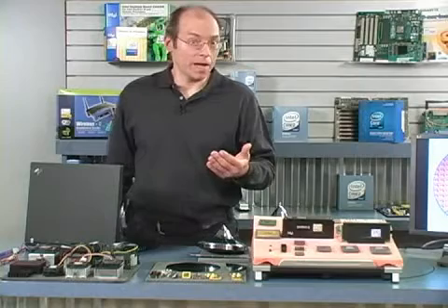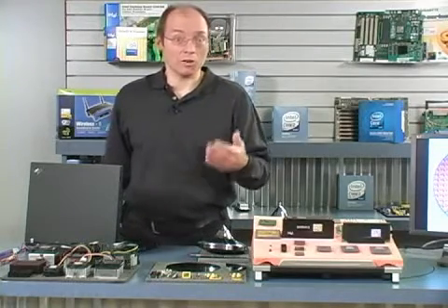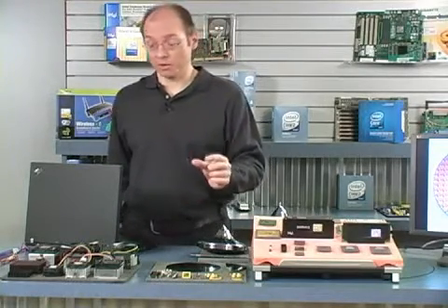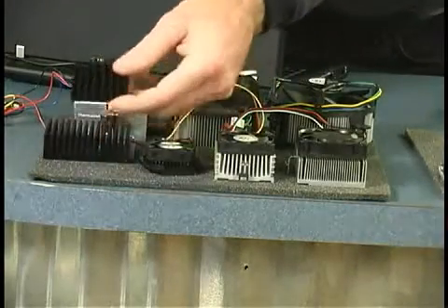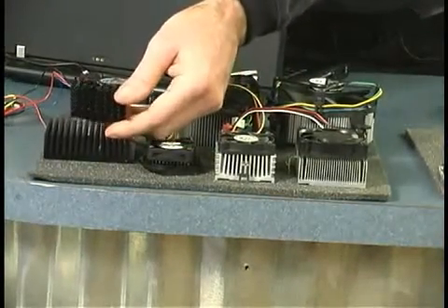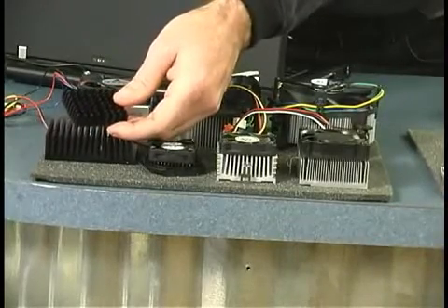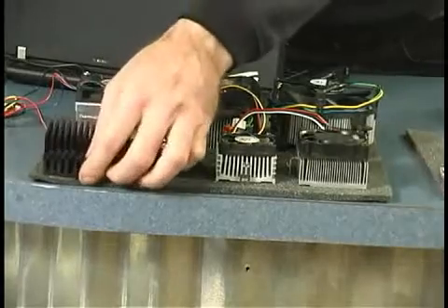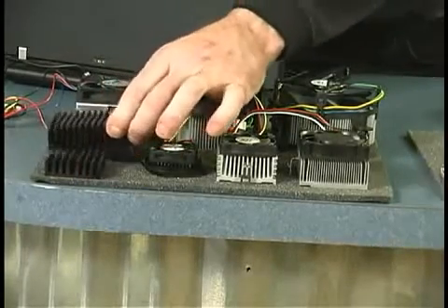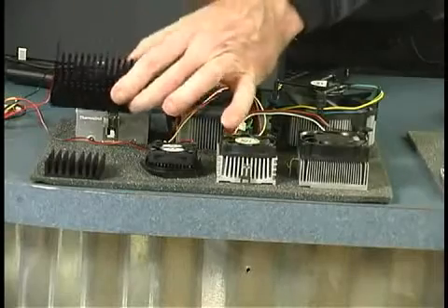But when we started getting past 33 megahertz, when we went to 66 megahertz, 100 megahertz and faster, we started to require cooling. This was what was used on some of the early processors that required a heat sink, and as you can see, it's just a passive metal radiator. No fan or anything. There was enough airflow in the system to cool it. When we got to 200 megahertz, we needed bigger passive heat sinks. This was for about a 233 megahertz processor.